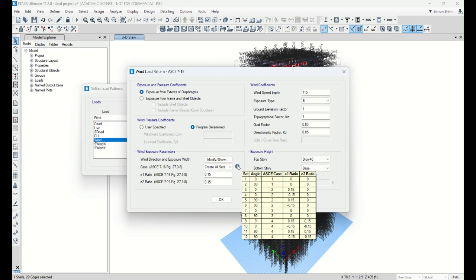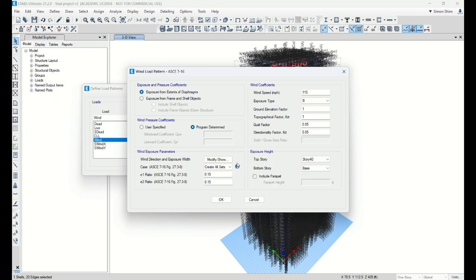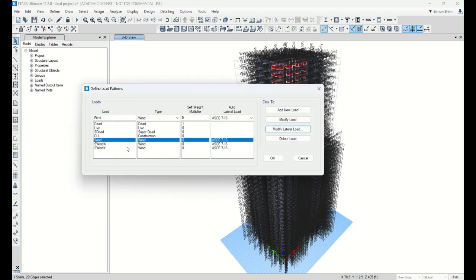I think there is some diagram I will show you later. But this is kind of common sense. The diagram is easy to see because the wind is blowing in any direction around the 360 degrees. But the wind doesn't always blow the same way, so the centroid of the wind forces doesn't have to always be at the centroid. Somehow we need to consider some eccentric effect. So W is the fully ultimate wind load cases we created here.